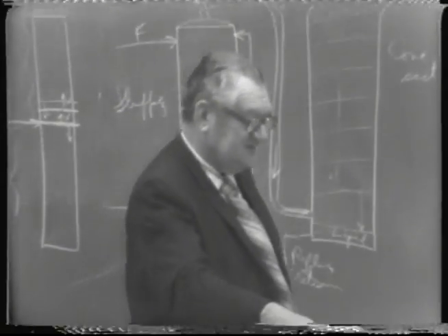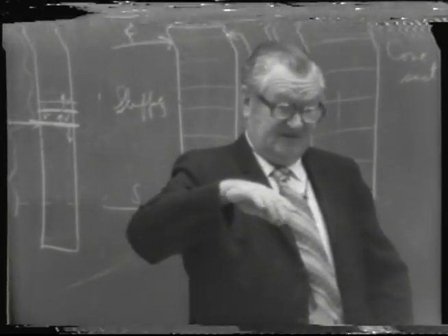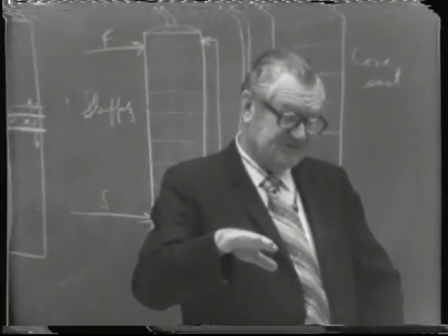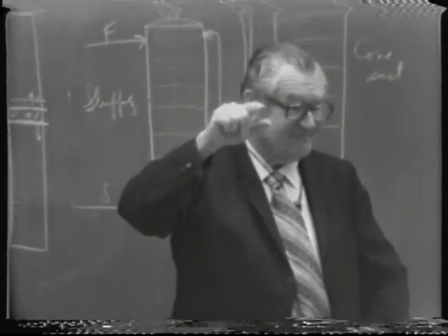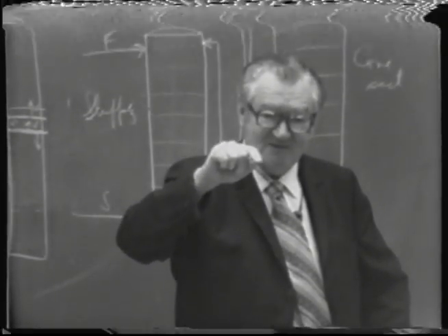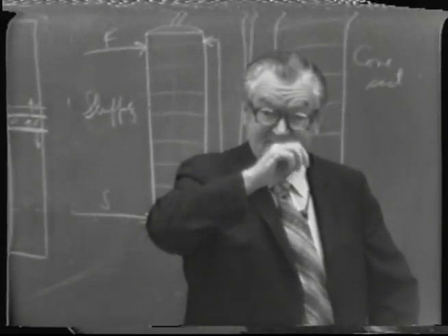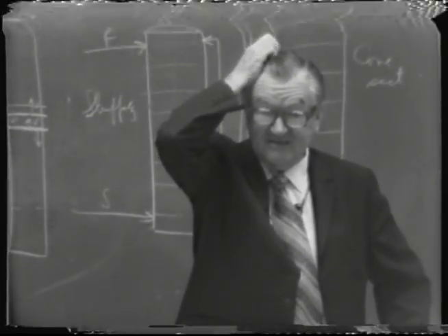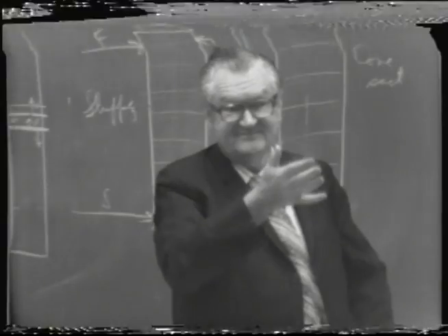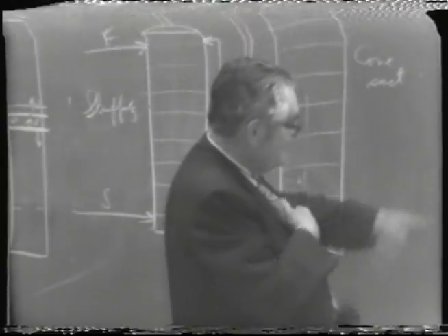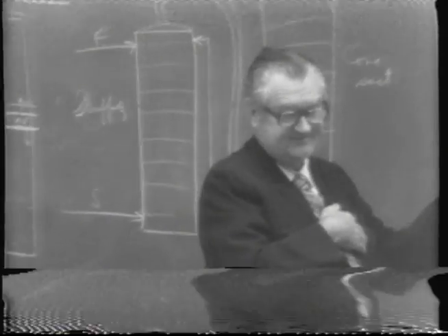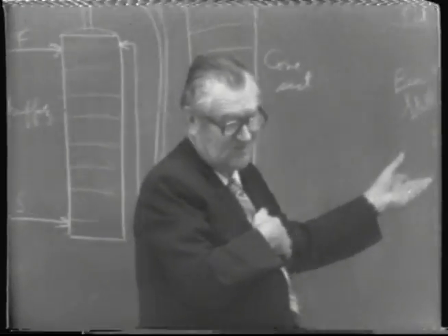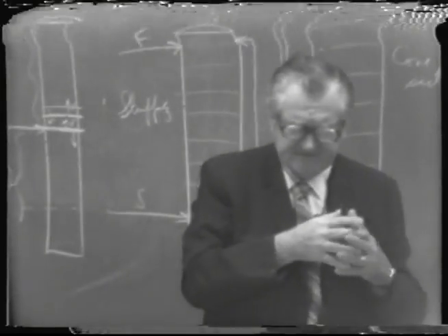Under those conditions, not only do the low boiling constituents go over in the top stream, but also the high boilers. The fusel oil components and the esters, fatty acid esters, they distill over in the heads. And so then the very dilute effluent out the bottom is concentrated in one or more columns after that.